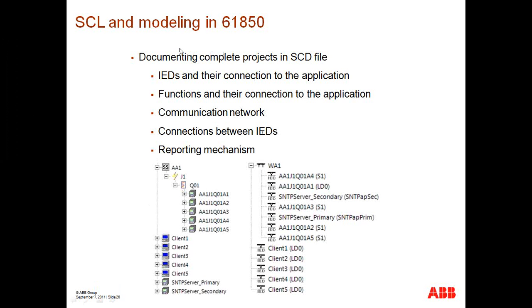On top of that, we also include support for an understanding of networks. You may have one, you may have multiple networks inside of a substation, at which point the SCD file also allows for that type of documentation. So again, we document IEDs and their connection to the application, functions and their connection to the application, the communications network, connection between IEDs, and then any type of applicable reporting mechanism.